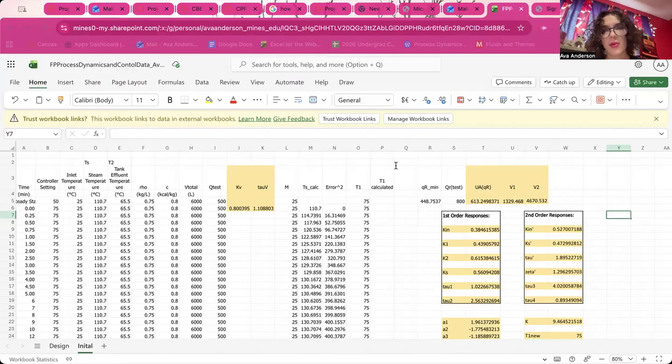I used a step input to model that, and the maximum deviation in the outlet temperature was found to be 6.35 times 10 to the negative 1 degrees Celsius at 2.34 seconds. That provides acceptable disturbance rejection under the design conditions. And overall, the two-tank recycle model provides a reasonable representation of the system dynamics. The PI controller was able to achieve stable and satisfactory performance at the intended operating conditions.